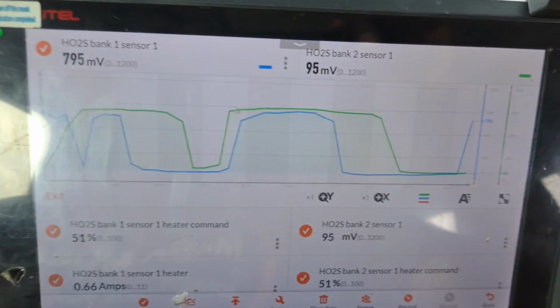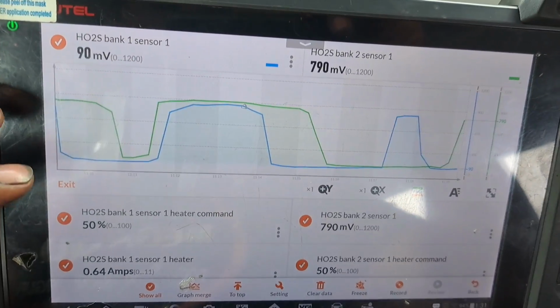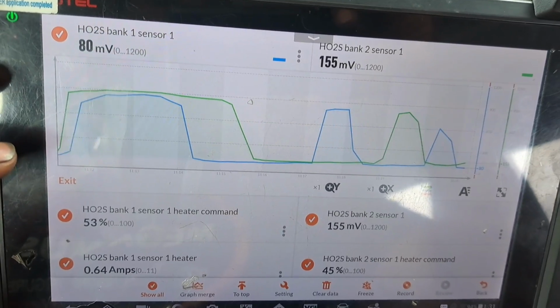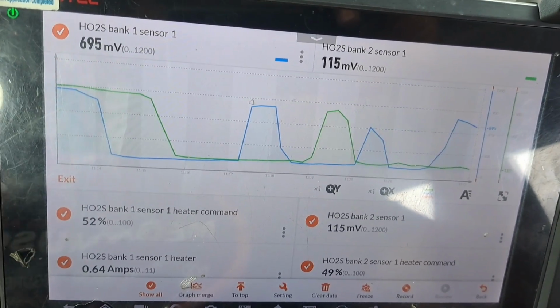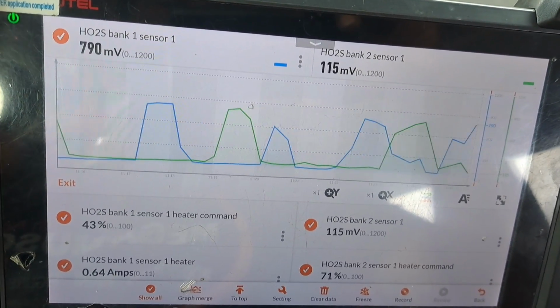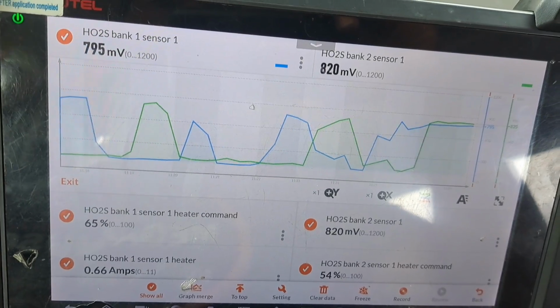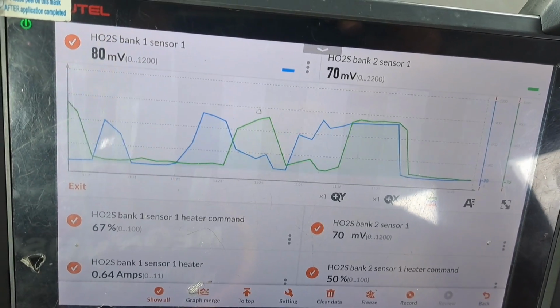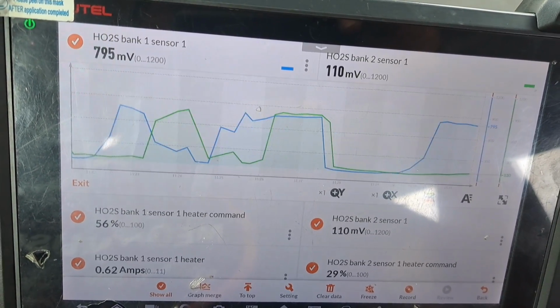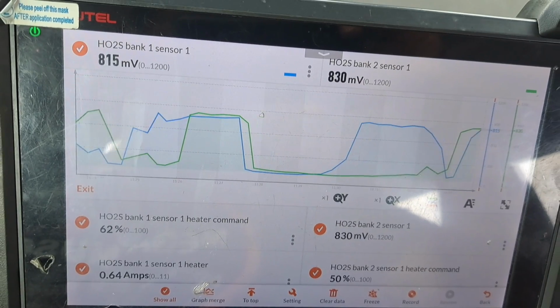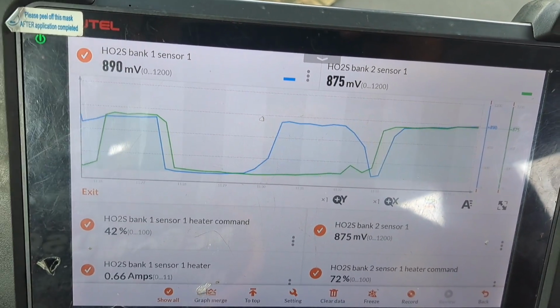So I just did catalytic converters on my brother's truck here. I'm dealing with a P219A, and I'm just trying to look at anything that may be some sort of anomalies in the live data. But I don't know if this data set is just too slow. It's 1 second per division with the live data.